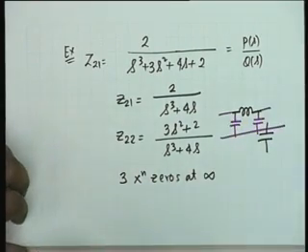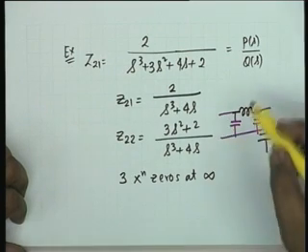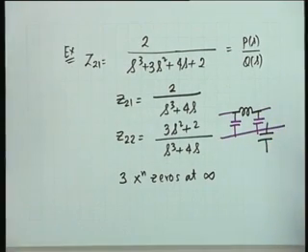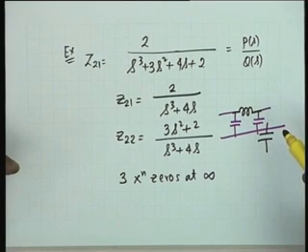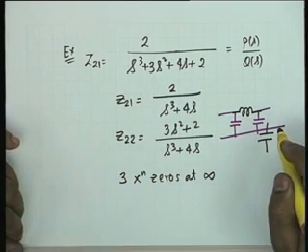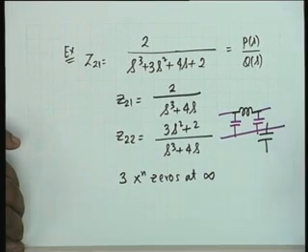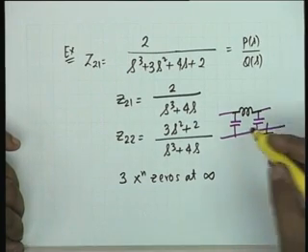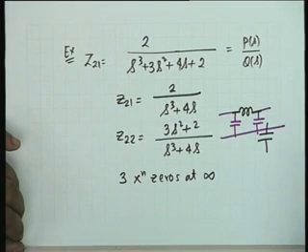It could not be 2 inductors and 1 capacitor, because the driving source is a current generator. For a current generator, anything in series is ineffective, and therefore this is the structure.